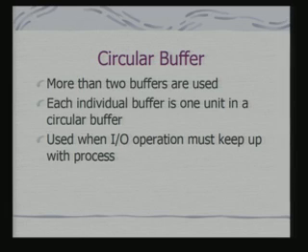This can also be done through a circular buffer. More than two buffers are used in a circular buffer, and each individual buffer is one unit in the circular buffer. If it is a continuous stream of data, when you use a circular buffer, effectively you are giving an impression of infinite storage, because you are entering data from one end and going through it just like a circular queue. So, that kind of continuous stream of data management becomes easier. If you are talking about a speech interface for a cellular phone, the buffer allocation for the receiver would be a circular buffer, because you really do not have an idea of the length of data, and it will be a continuous process.